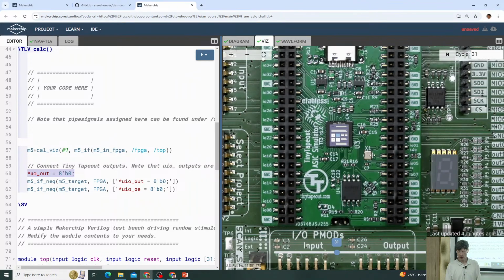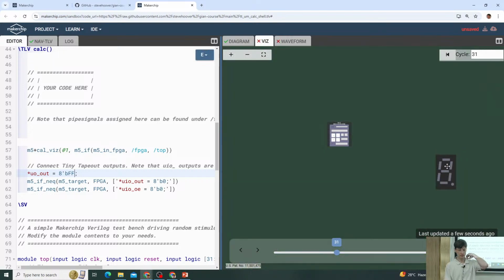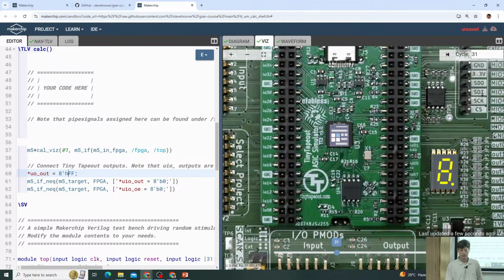We can see that in simulation. This is our 7 segment hooked up to this value, and we see that the segments never light up. So for example, if I drive this with FF, we'll see those segments are all lit. We'll see the design is broken. That's not a binary value. Let's try hex. So all the segments are lit up. So that's our output, 8 output signals.